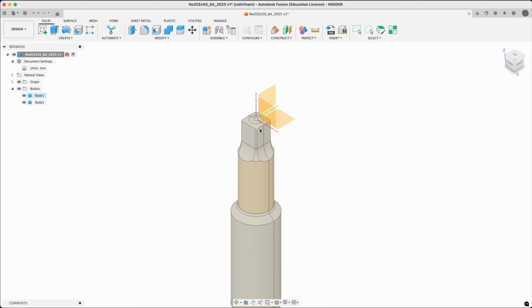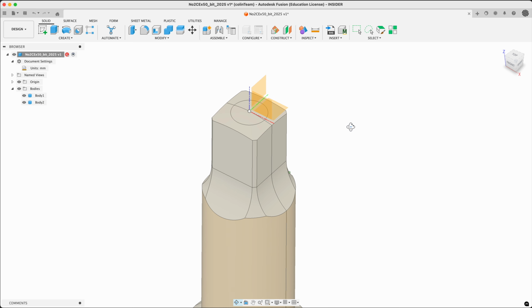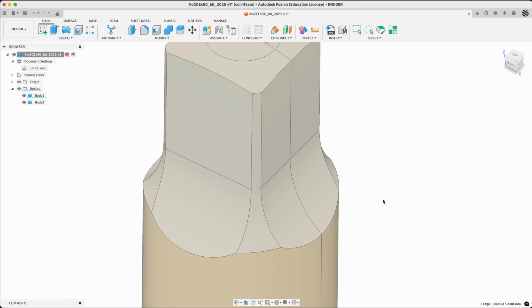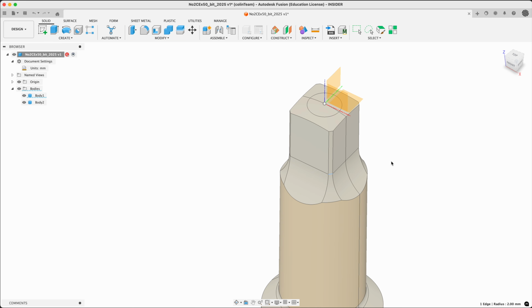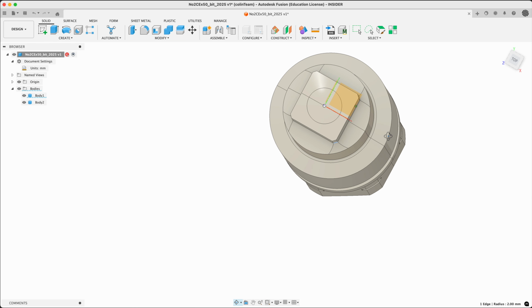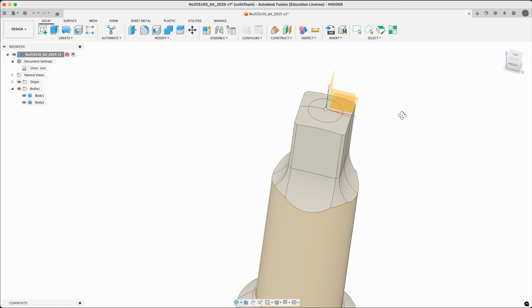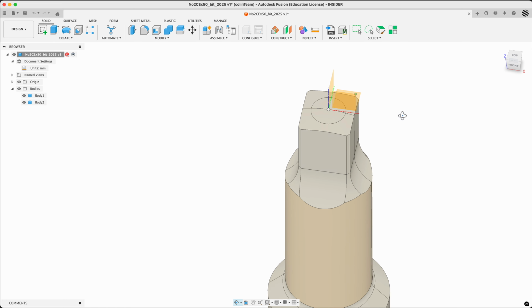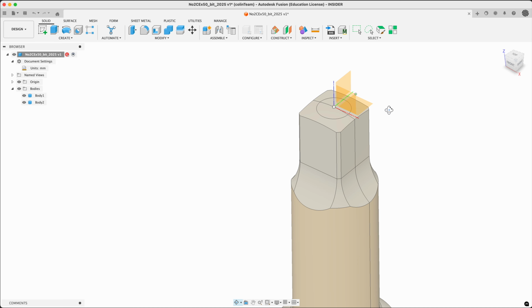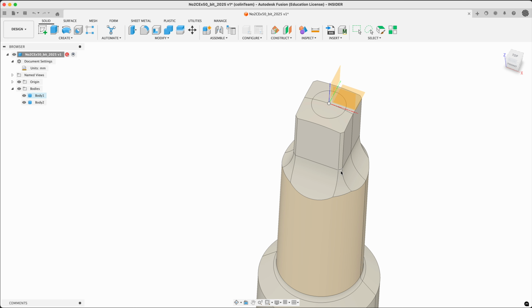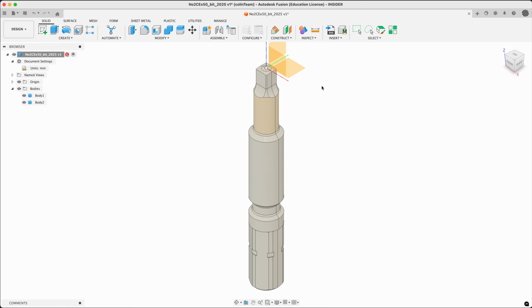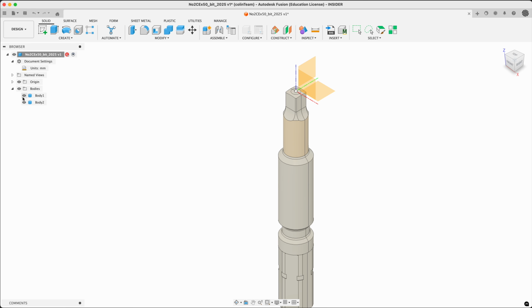One thing that the problem is here, for example, we know that this here is a radius. So it's a swept sort of revolve, if you want to think of it that way. One problem is that we cannot get that directly mapped onto our sketch. So keep that in mind while we're working away here. We're going to come back and split it again. We have 2 bodies. If your bodies are not open, just open them in the browser.